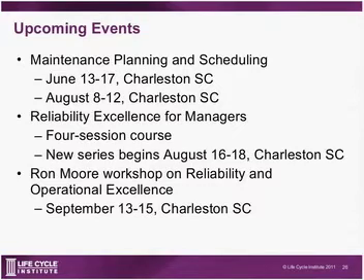So in your discussion, evaluating a before and after, you perform an OEE analysis to determine if on line A, if I'm at 50% today, I do these 4 actions in order to either increase our quality, increase our rate, or increase our availability, and measure our OEE after that.